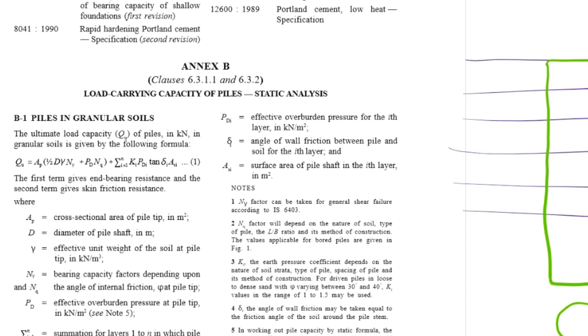So this layer has N equal to 10. This soil is sand. Here this one is also sand, so N is equal to 12, sand. This is N equal to say 5, but c is equal to 10 kg per centimeter square. Then we call it a mixed sand and sandy clay. We may also have clay, complete cohesion. We may also have some N value in between. So this way we have a soil profile.